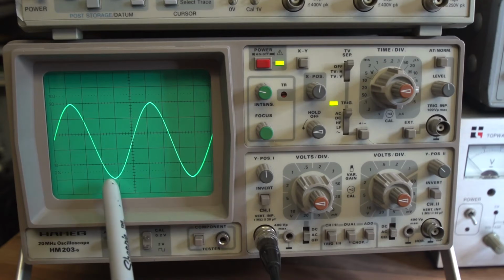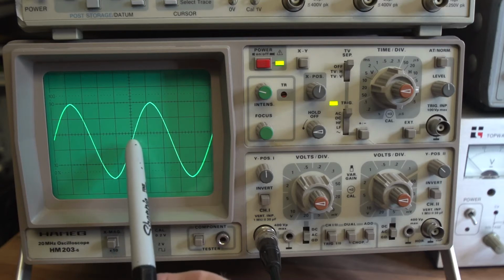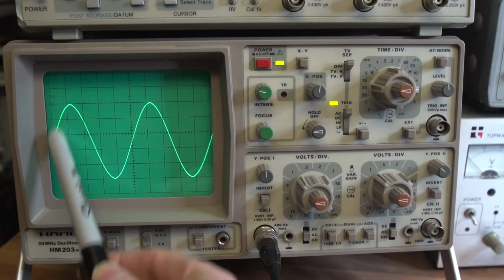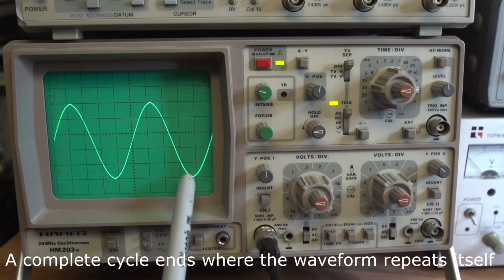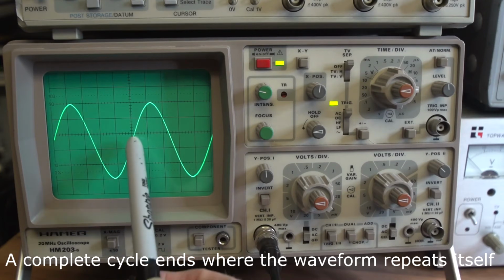So keep going, then you hit this part, well that's a different voltage, so that's definitely not the end of the cycle. Now what about this one? Yeah, it crosses through the 0 and it's going positive again. So what you can say is that those points are the same. That is one entire cycle. It goes up, down and up, and then it starts to repeat the next one. So you can discard all of that and just use this part here.